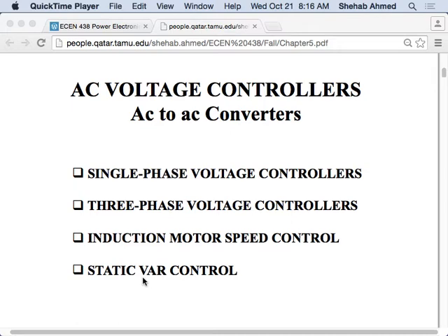As you will see in 459 later, if you operate the power system in leading power factor, you're actually limiting the capability of the generators to send power. That's something we will derive and talk about in 459. But for now, generators in the power system like to operate in lagging power factor. How much lagging power factor? That's up to the utility, really.